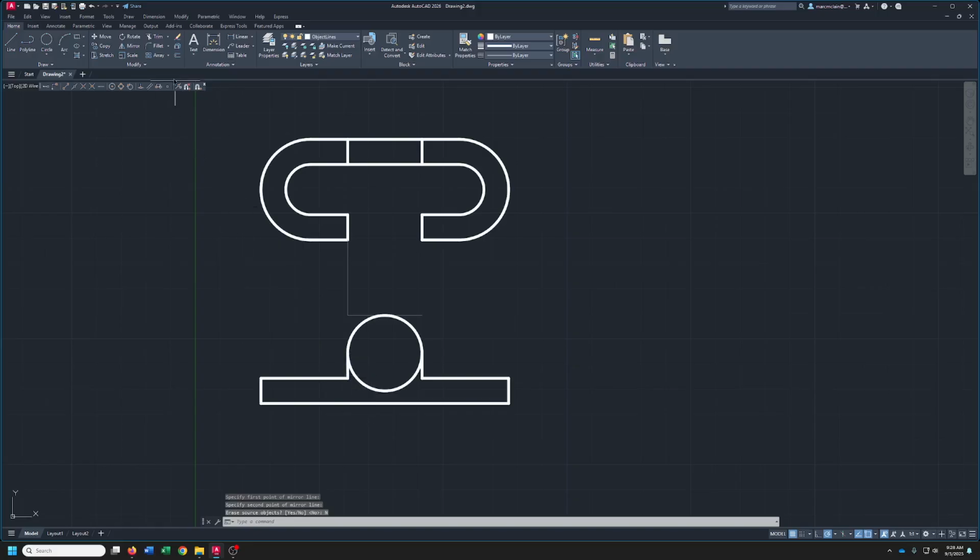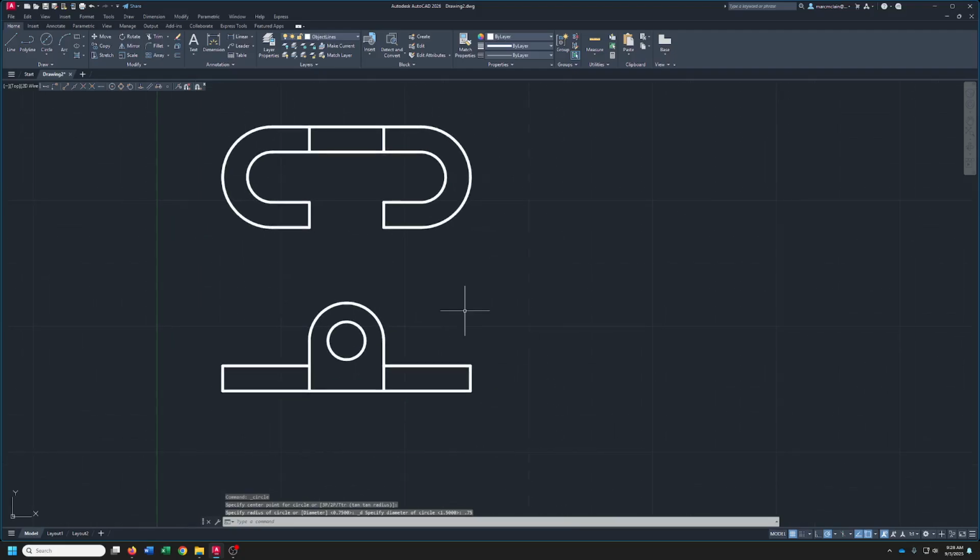And this line is going to come all the way down, so I'll just go up here where it says trim, pick the arrow, go to extend that one, extend that one. I'm going to go ahead and blast these two out and trim. Right there. Okay, one more thing to do. I just need a diameter of 0.75. Midpoint of this, there we go, 0.75. Front view. See how easy this is?